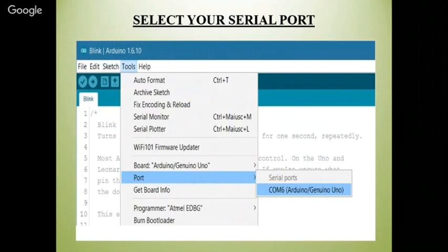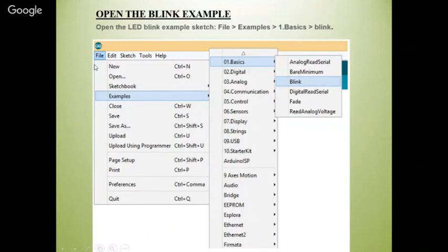For checking this Arduino board, I have to go to the examples. Predefined examples are there. There is no need to write the program in the beginning. You can learn from the start, and then you can make new programs. So for checking whether your board is communicating and working properly, you have to go to File, then Examples, then Basics, and then Blink. You can note that down.